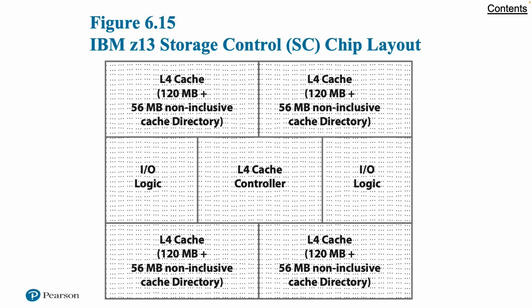Well, let's look at things for the IBM case. The IBM z13 system uses EDRAM at 2 levels of the cache hierarchy, as we're showing. You can go back to figure 4.10 as well to give you more context for what we're talking about here with the IBM z13. Each processing unit, PU, chip with up to 8 cores has a shared 64 megabit EDRAM L3 cache. This is an example of an EDRAM integrated on the same chip as the microprocessors.